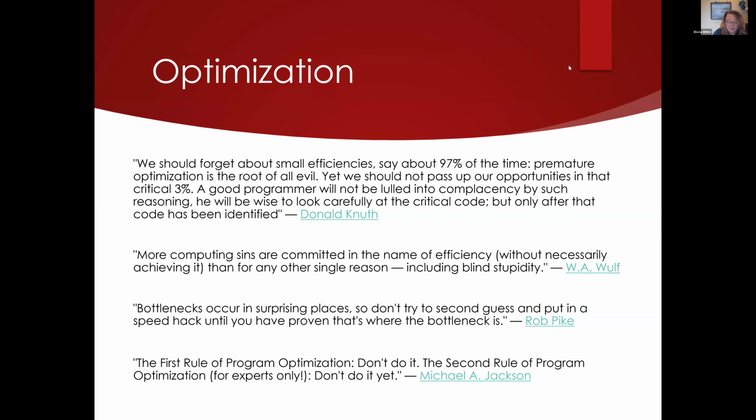Once RAM is optimized so that it's shared between two modules, the encapsulation is forever damaged, and changing either module may break both. And when you run out of code space, a single small bug may require you to change code in 15 locations to make space for the fix. When you ask an embedded software engineer why they did something, and they reply, "That's how it's always been done," that may be a cop-out, but it also may be an important statement about the fragility of a system that's been optimized to work with the resources available to it.